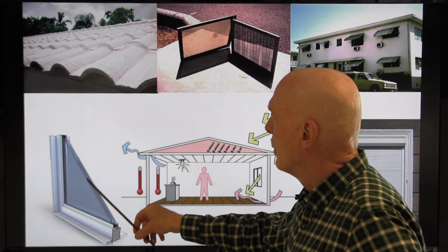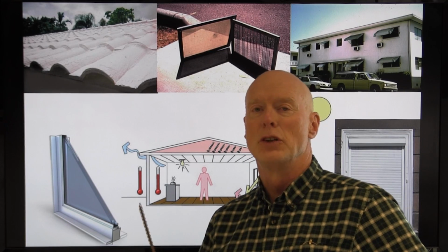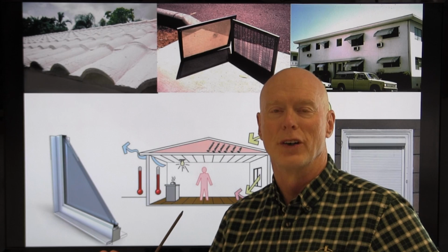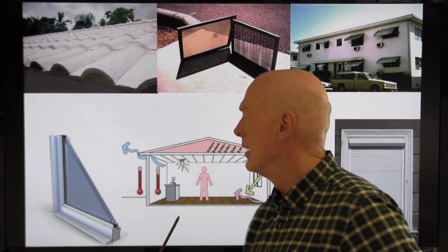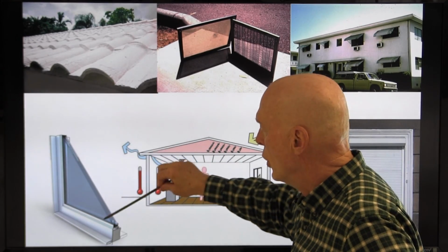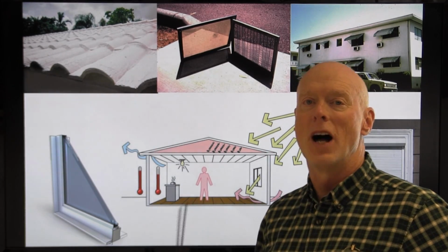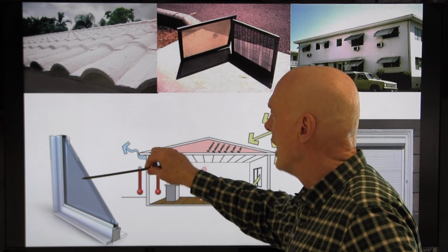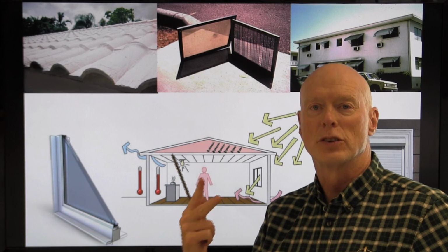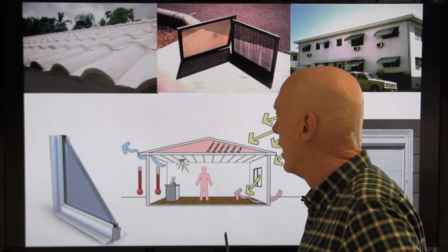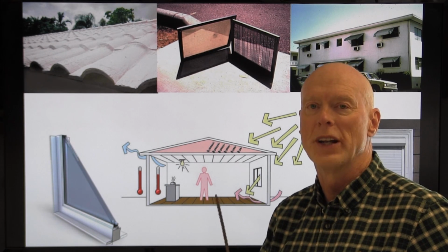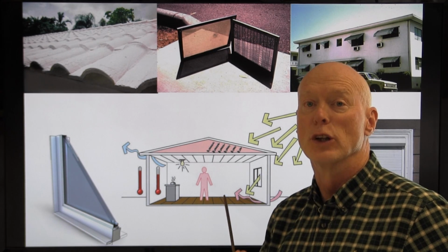The modern triple pane window can give you a very clear, unopposed vision of the outdoors, let a lot of visible light in, but block most of the solar heat, because you can put two low E sun blocking coatings on this glass. So you have 3 pieces of glass, you can have 2 coated surfaces, and you can get that solar heat gain coefficient down to, say, 15 or 20%, or even lower than that.